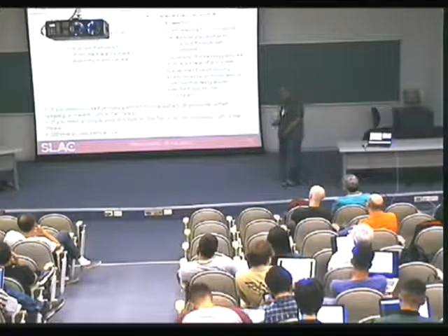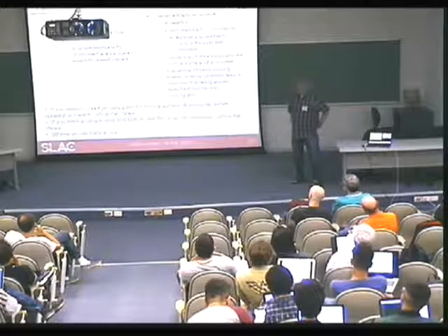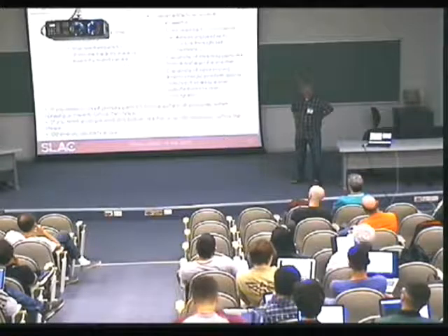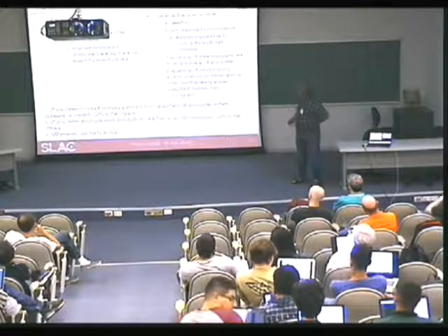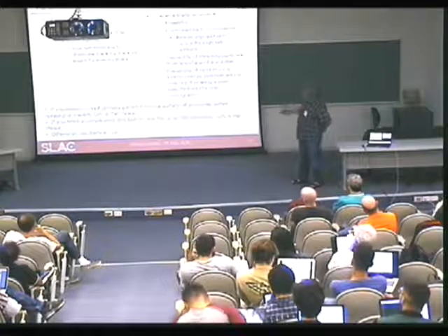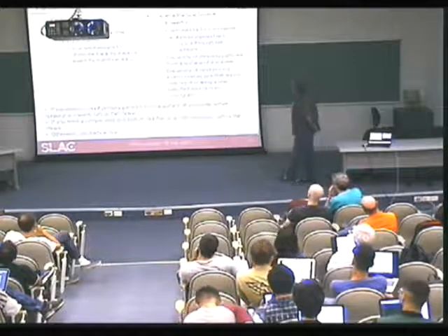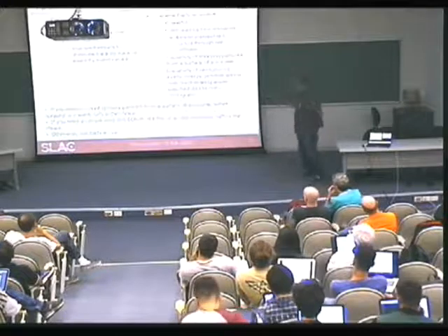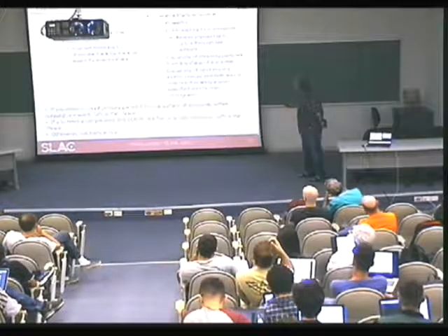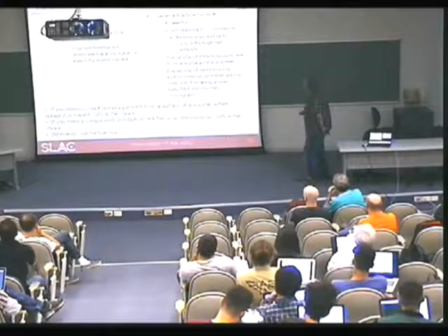So here's a comparison: particle gun versus general particle source. People like the general particle source because they misunderstand it as powerful. Yes, it's powerful, but it's dangerous. The particle gun is simple and naive. It shoots one track at a time, it's easy to handle, and you really understand what you're doing. GPS is very powerful, but can be controlled only by UI commands. It's almost impossible to control through the set methods. Just forget about it.